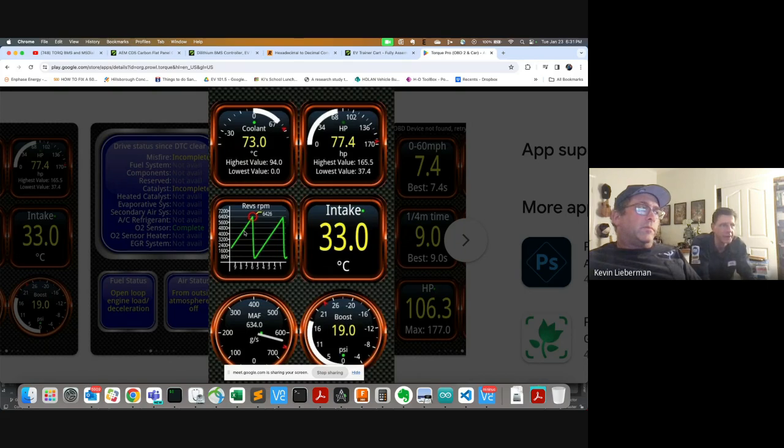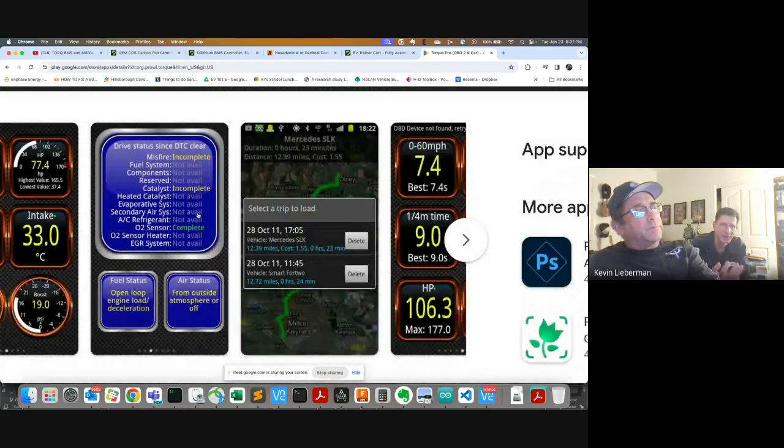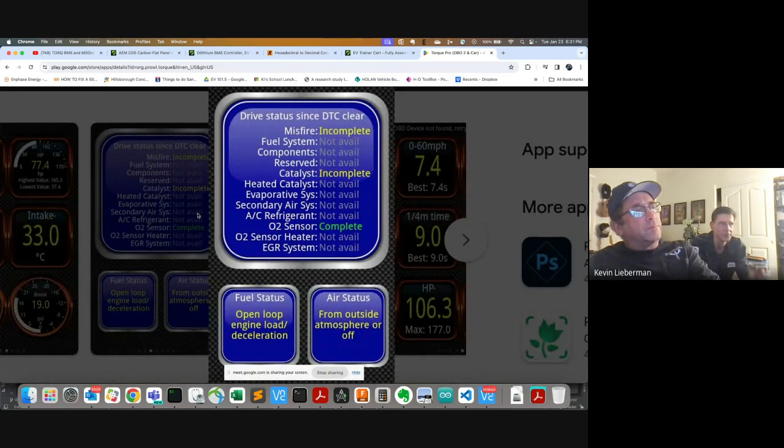I think a lot of it is, we're talking about it, but I think a lot of it is just have exercises where we just do it. Like if we're going to do a class, like in the 101 class, where the students just bring their laptop and everybody downloads the Torque app if you don't already have it. Okay, now open Torque and connect to your Bluetooth. Okay, now we're going to take the CAN sniffer and sniff out whatever hexadecimal number and pair it up. And then we're going to practice taking one CAN message and marrying it up with the Torque.